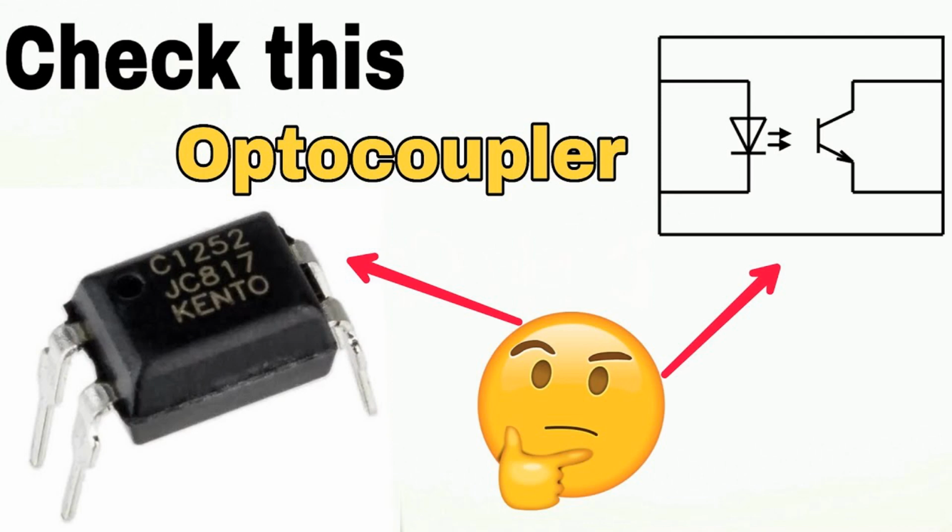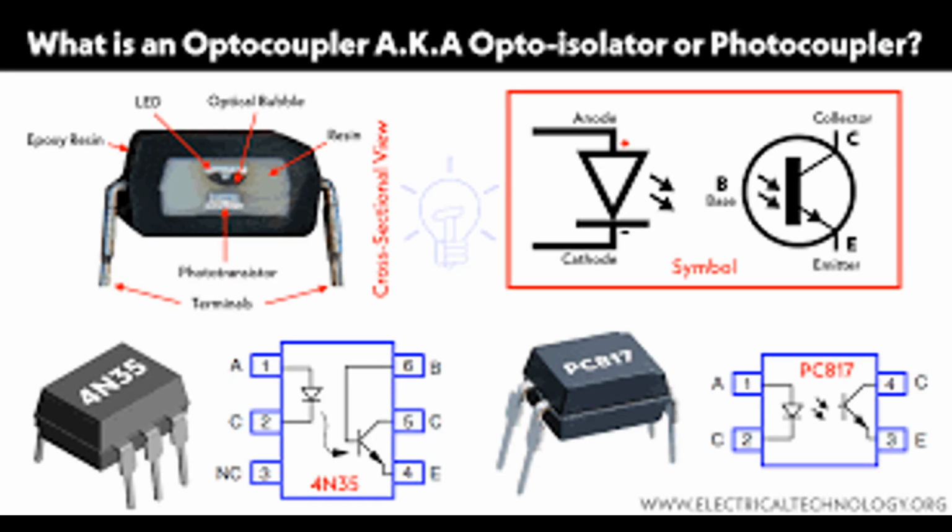Signal rectification and conversion. Signal conditioning can include rectification, where an AC signal is converted into a DC signal, or vice versa, to suit the requirements of a particular application. Signal filtering. Filtering can also involve the removal of DC offset or bias in a signal to center it around 0 volts. Signal scaling and offset. Adjusting the range or scaling of a signal can be necessary to match the input requirements of downstream equipment. Offset adjustment may also be needed to shift the signal level.